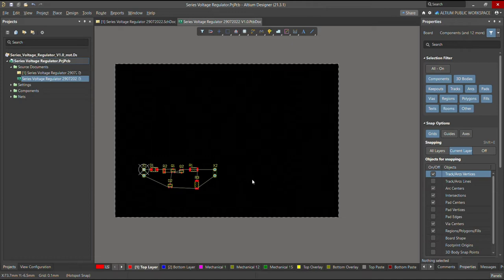Apart from that, I'm also going to tell you how you can import the 3D step model, which, for example, you received from your mechanical design department, and which components are available in that 3D step model apart from your PCB step. So how you can then disable or enable them.